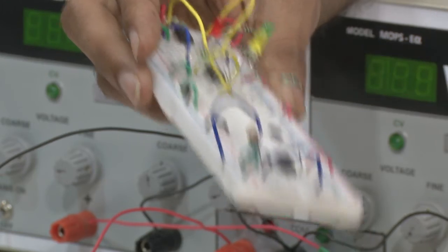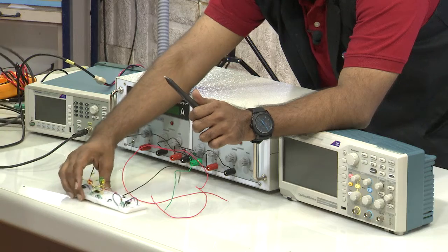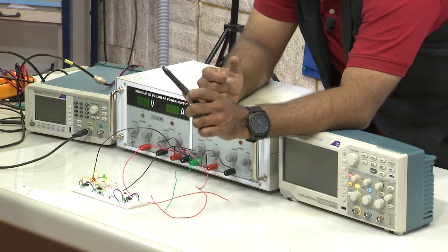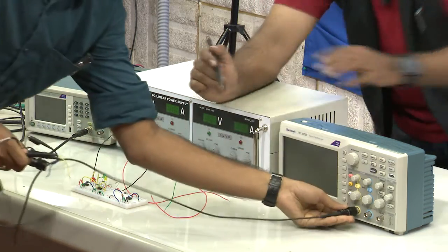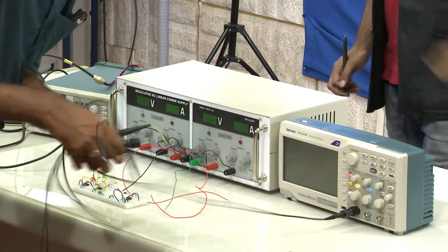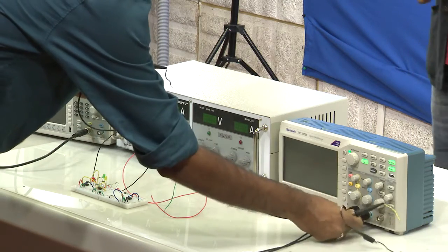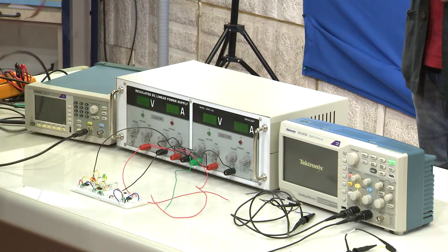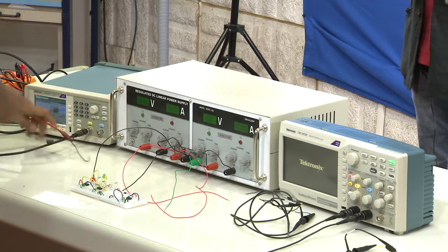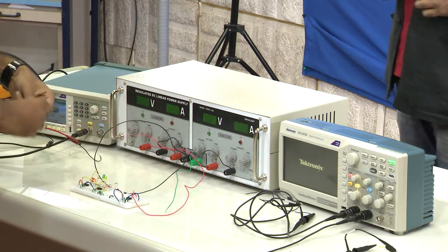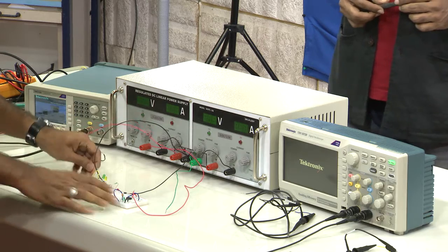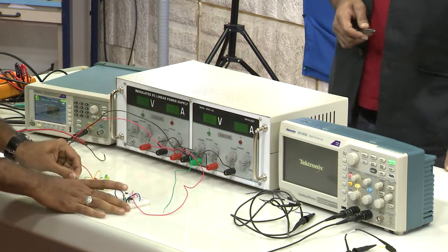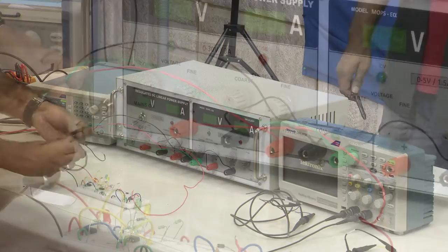This is what we will do today, and for that we have to attach the 5 kilohertz signal. That means we have to use the function generator. So, we have our DC power supply, then we have the function generator, and we have the oscilloscope. Three things we have: DC power supply, function generator, and oscilloscope. The first step is connecting the bias voltage. So, plus 15, minus 15 across the op amp, we can see this.